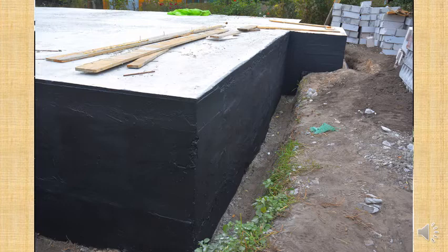And you can see they've built a big solid platform there to build a house. But they've painted around the edge there with this black tar paint. And that's to keep it waterproof. That's to stop water getting into the low quality concrete and potentially damaging the foundation over time. So it's creating a waterproof barrier.